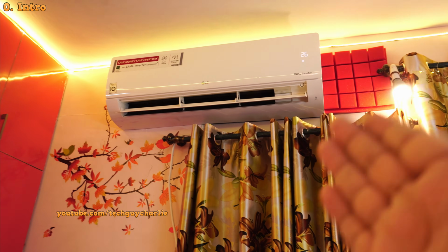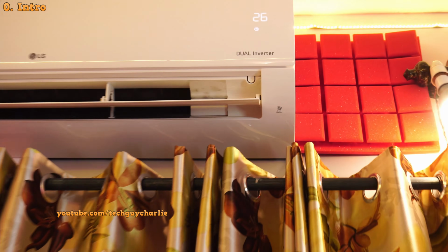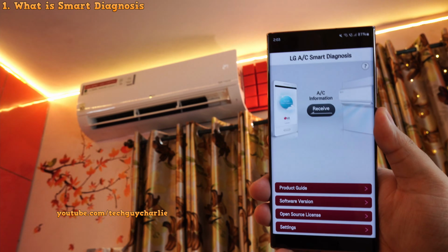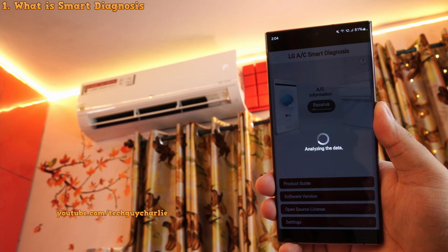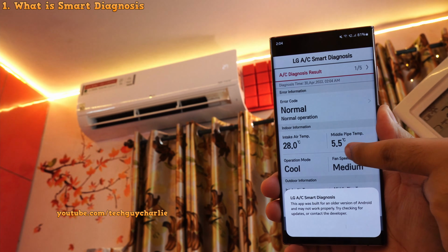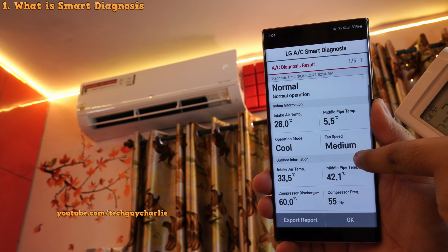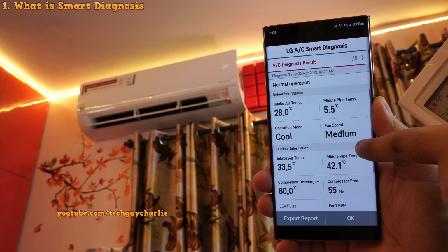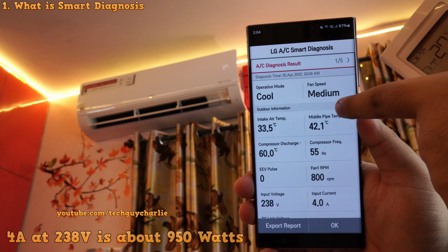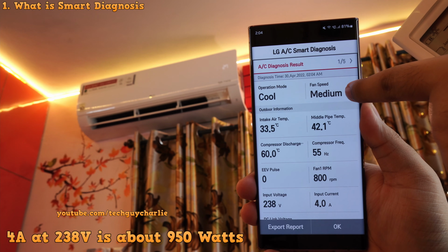Alright, so if you've got an air conditioner from LG, you might have noticed this label which says Smart Diagnosis. This is an awesome self-diagnosis feature of LG air conditioners, and it will show you quite a bit of information on your smartphone, such as the air intake temperature of the indoor and the outdoor units, compressor frequency, gas discharge temperature, and lastly it also shows the input voltage and current, and using this you can calculate how much power your air conditioner is using.